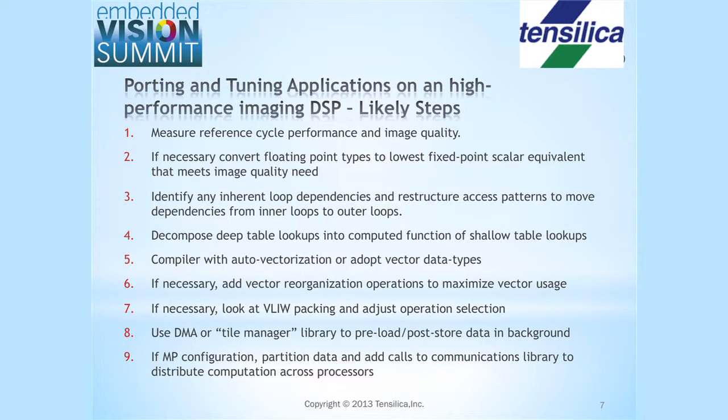But in importing a lot of code, we've generally found that having a choice of 8, 16, and 32-bit gives you enough resolution in enough circumstances that you're generally fine. But you will have had to have looked closely at certain critical steps where, for example, you can leverage normalization operations, or where there are numerically unstable calculations that you might be wanting to do to make sure that you don't lose a lot of precision when you go through a float to fixed conversion.